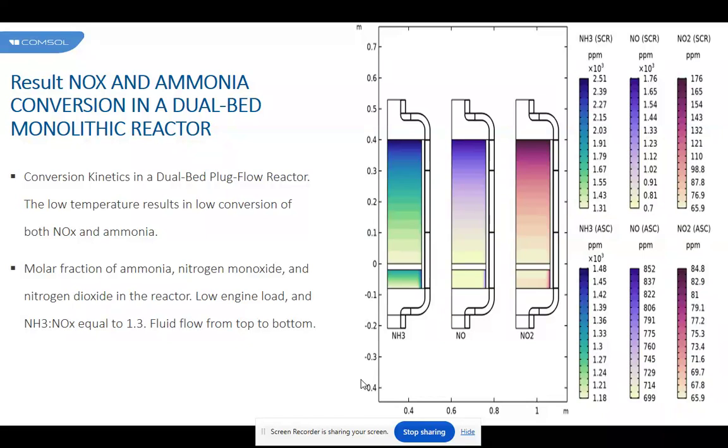Although the catalyst formulation varies depending on the mode of engine operation, the heart of the catalytic converter is a multi-channel honeycomb monolithic substrate, the walls of which are covered with the catalytic washcoat. The monolith substrate can be made from either metal or extruded cordierite. Here we limit the discussion to the more common cordierite versions. Furthermore, we discuss the straight-through design and not the type used in wall flow filters.